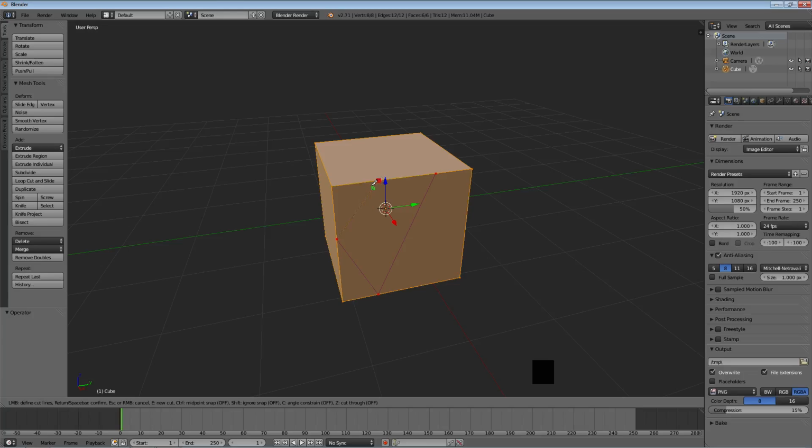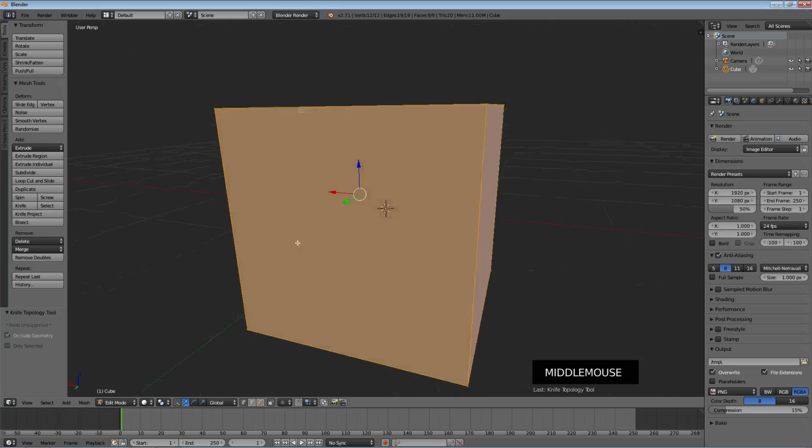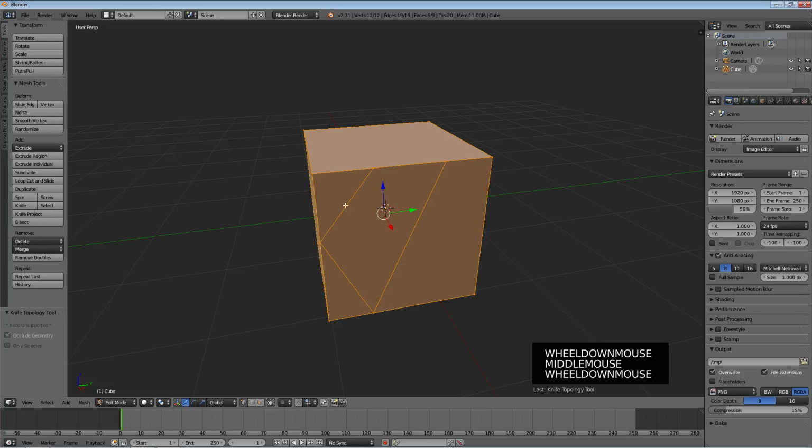When you're done, you can read along the bottom header here. It says you can hit return or spacebar, or you can hit escape to cancel. So I'm going to hit return, and notice I now have these extra vertices in here and extra lines. This face has been subdivided very custom because of that knife cut. It's like I literally took a knife and cut new lines in there, and it automatically adds the points where I put the points down.